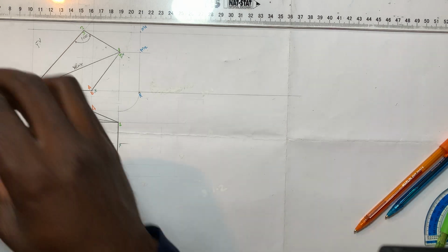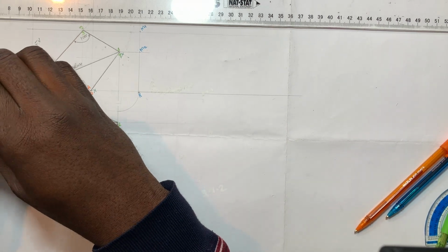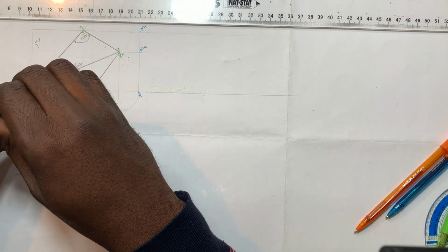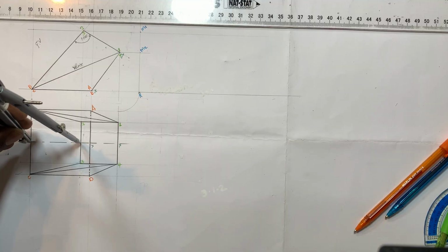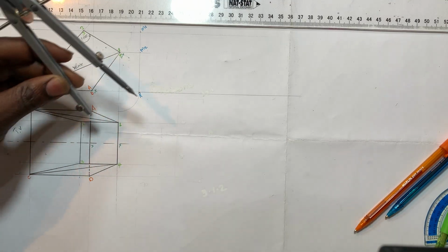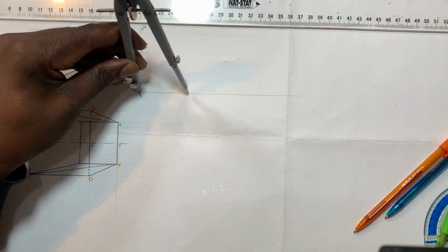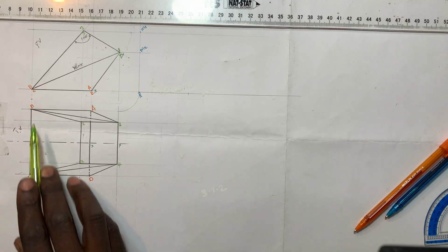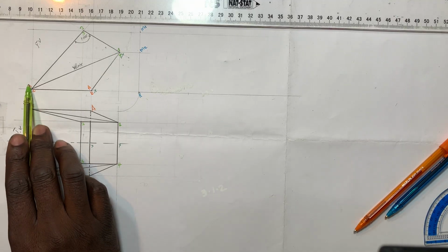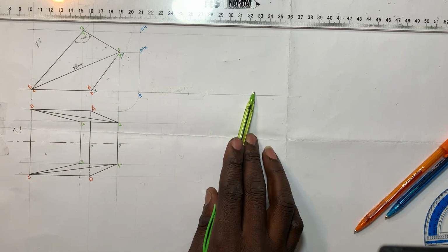Place it here. Further extend it to the center of 2, 3. This is it. Understand? This is it. Now, without disturbing my drawing compass, I come and place it at R. Then I mark. Understand? So this is the height, which is BC. That goes BC. Once it touches there, goes horizontal.